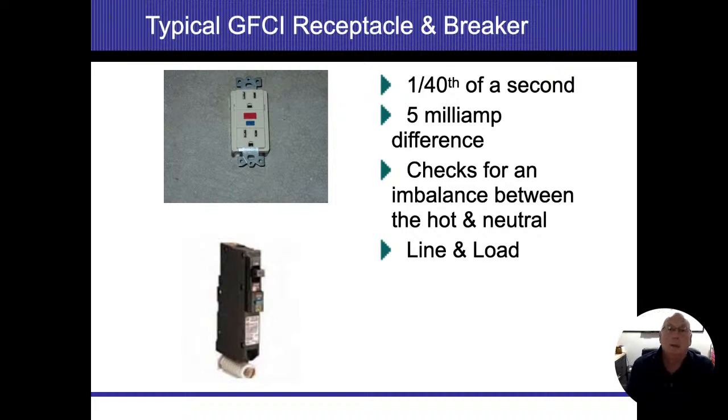Now, I always get mixed up on how fast these things are supposed to work. I know I've used terms of 1/50th of a second, but 1/40th is the right number that's up here. But that's just fast. 1/40th of a second is almost instantaneous. We did a couple of tests on GFIs, and I remember we had a light bulb that we had hooked up to a ground rod outside, so we created a ground fault, basically, and the ground conductors and water services.